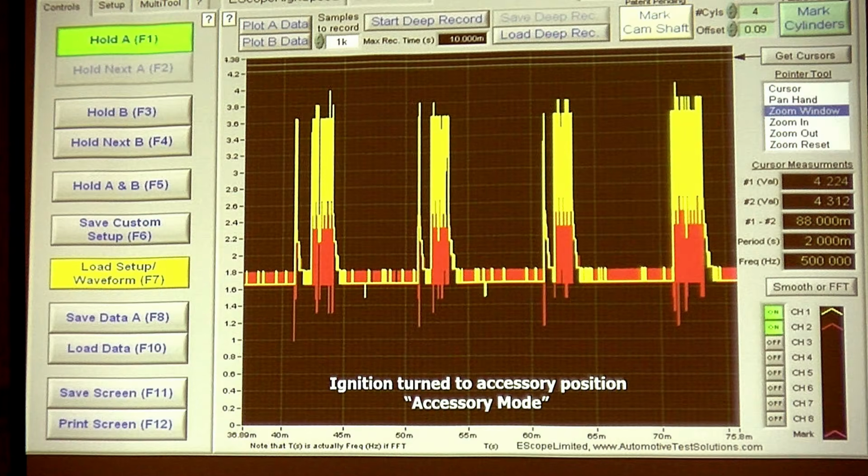So the waveforms that you need to know, that's one you need to know. That's accessory mode. If you get on a bus and you see that 1.8 volts moving to 3.6, that's accessory. You're not powering the modules. That's what that's telling you. It's like when you put your key on and you're in accessory mode, you didn't light everything up. You're only part way there. The bus woke up, but he is still asleep, guys. Does that make sense to everyone? He's not ready for active communication.